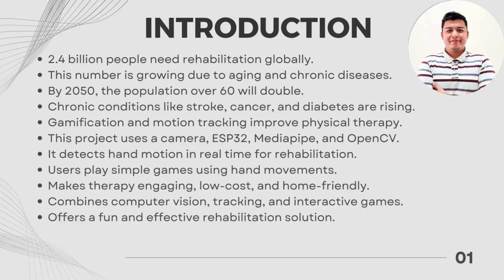Gamification and motion tracking are becoming popular in physical therapy through vision-based technology. This project uses a camera, ESP32, MediaPipe, and OpenCV for real-time hand motion detection. It helps with hand rehabilitation by letting users play simple therapeutic games using their hand movements.